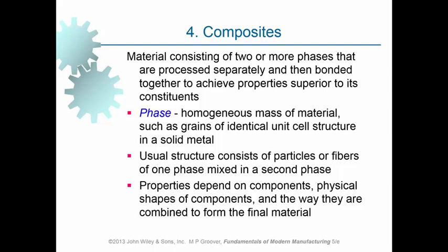And once this material, that is a composite material made of polymer and an embedded phase, are subjected to forces, those strong particles that are inside of the polymer increase the strength of the material, so it can be subjected to higher amount of force and stress before it fails.